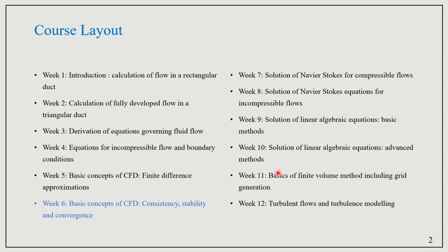So by now, we are almost clear on what we require from computational fluid dynamics. What we are doing is solving a system of equations to get the solution for that particular problem. If pipe flow is our problem, we need to know the velocity and pressure at a particular location, or if there is heating involved, the temperature. If it is a pure cold flow system, we have the continuity equation and three momentum conservation equations.